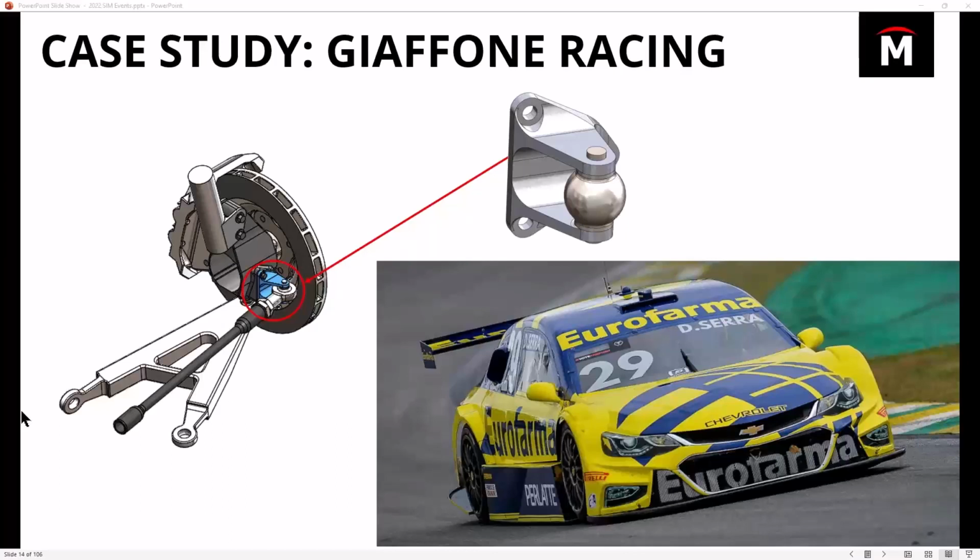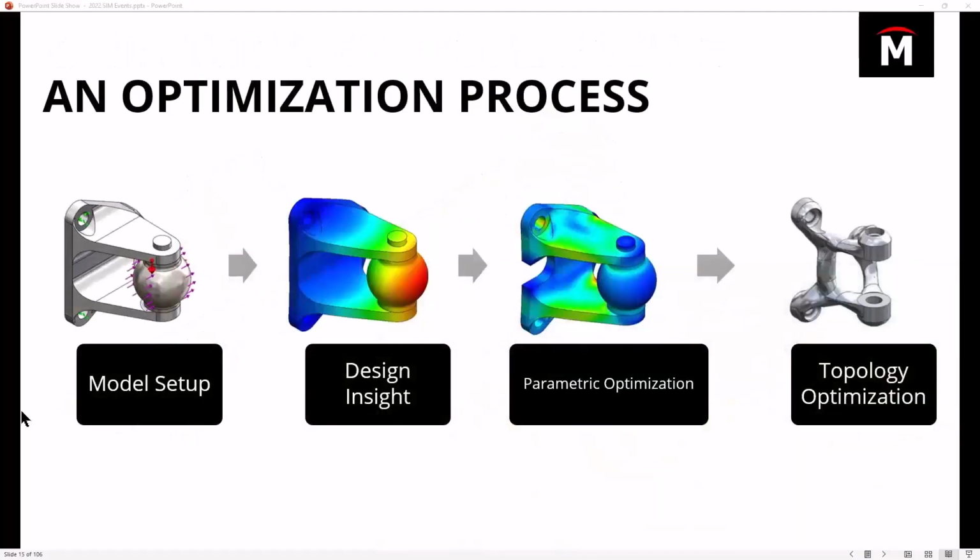And they thought, okay, well, this is a cast component that comes with a car. It's pretty heavy. We're making all sorts of things out of aluminum that's easy for us to machine. We know that aluminum generally has better fatigue lifespan, but it's not as strong, right? It's going to flex more. It's going to have problems probably. Can we just swap this out with aluminum? And because we have SOLIDWORKS Simulation, it's like, well, let's find out the answer to that question and let's take this further and then optimize it if it survives.